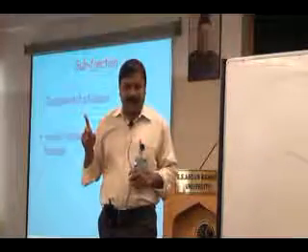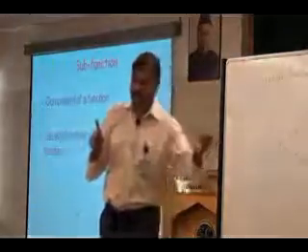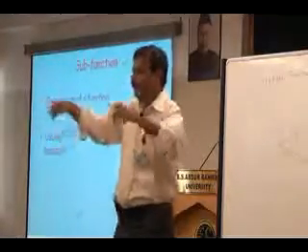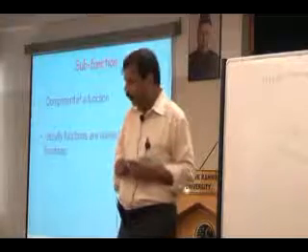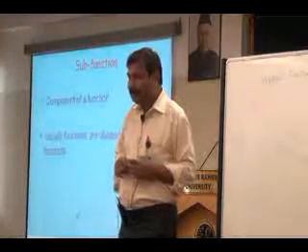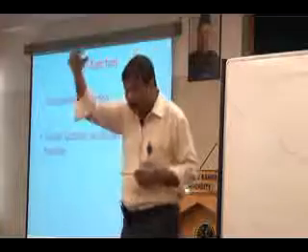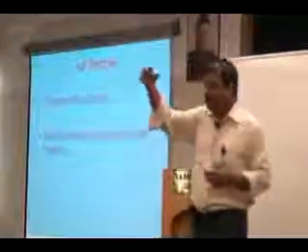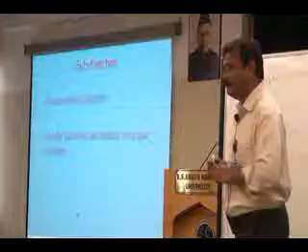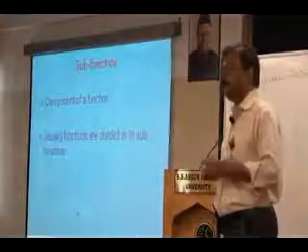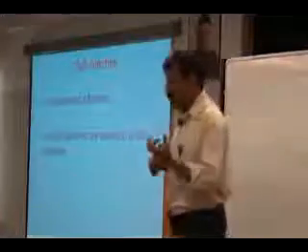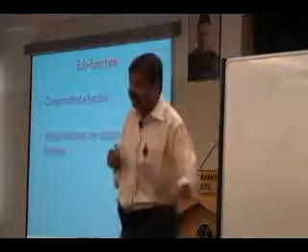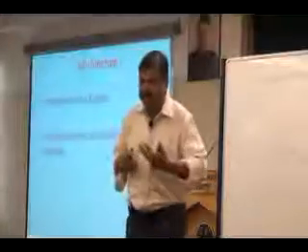I don't know whether you are getting my point. That is called a dashpot. Many of you might have changed oil in your bike suspension. Have you ever changed oil? You have to change the oil in your bike suspension periodically. The purpose of having oil there is that the piston has to move against a viscous oil, in that process dissipating the energy absorbed.